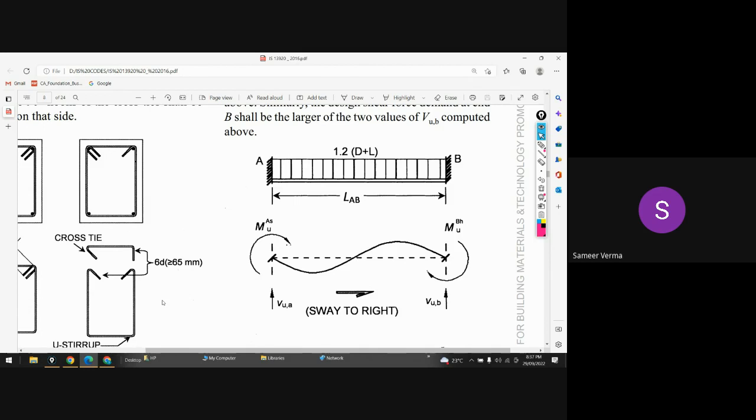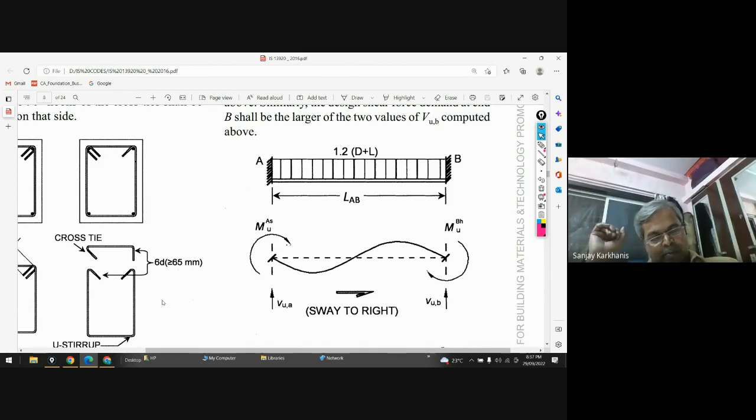Yes, sir. That was your basic assumption. और उसकी वजह से आपने R equal to 5 या R equal to 3 या R equal to 7 यूज किया है, जो भी. But you have accepted some sort of damage in your structure when it is subjected to lateral loads arising due to seismic activity, right?